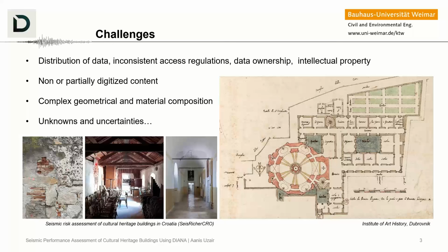The problem also is between the connections and how to deal with these connections in a realistic way. For example, in this case, you would see that the floor is connected to the walls, but the connection is rather uncertain. So if you really look into it, you would assume that there is no connection between the wall and the floor. And in that case, the damages to the wall come mostly in the out of plane direction, which can only be resisted through proper connection with the floor system, and they are sometimes very difficult to analyze because the out of plane mechanism is very localized in nature.